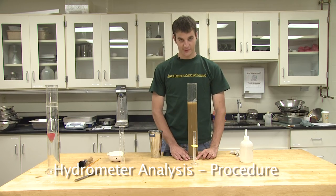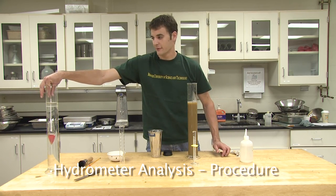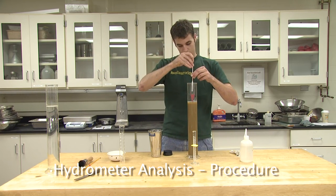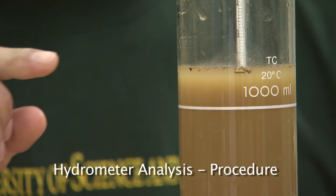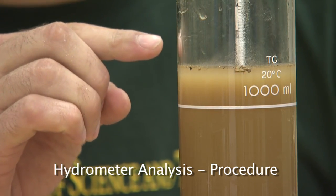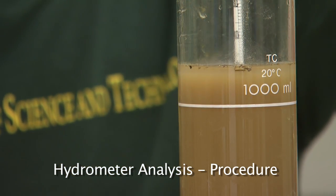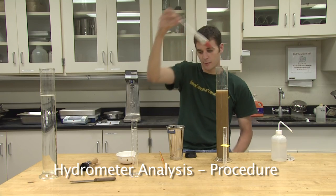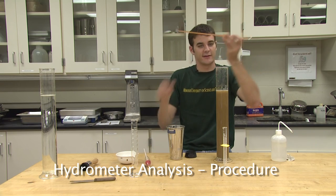After 2 minutes of placing the jar on the table, insert your hydrometer and take the first reading at 2 minutes. Record the reading on the hydrometer staff at the top of the meniscus of the dirty water. After the reading, remove the hydrometer, place it aside, and insert the thermometer to take a temperature reading.